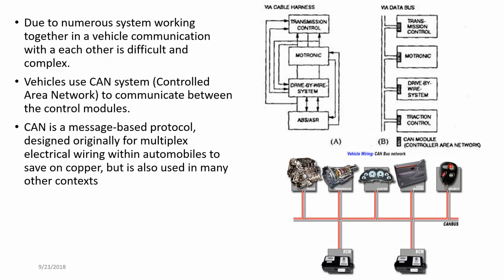By using this, the system can communicate digitally while reducing the necessity of communication lines. It only has two buses, and those two buses are enough to communicate and control the whole vehicle. This is not happening outside; it's mainly for communication inside the engine control modules, only for communication between control modules.